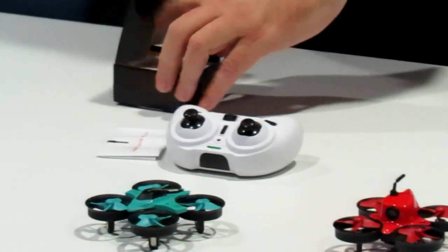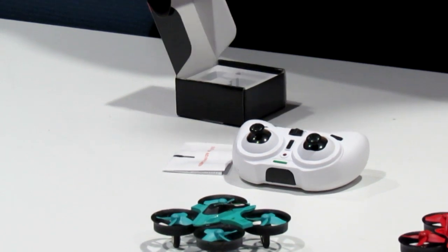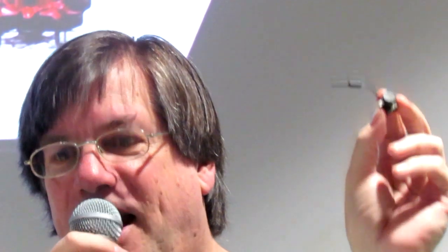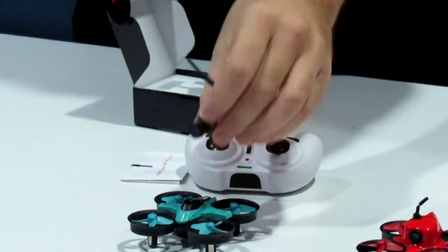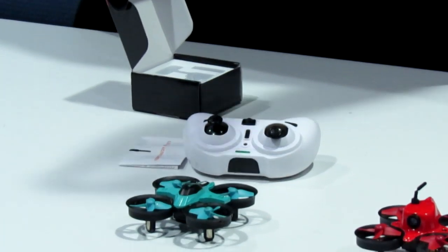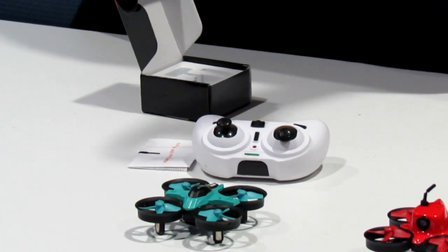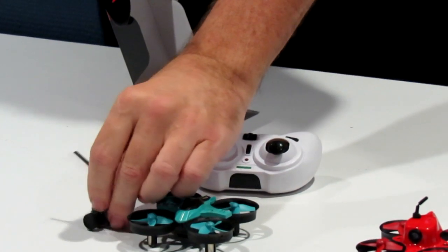And I found online you can buy these little tiny 1.5 gram cameras that transmit NTSC on 5.8 gigahertz. You can get these for about $4. And there's a lot of YouTube videos that take one of these and glue it to the top or bottom of one of these. And so now you have a drone with full video FPV that you can fly around for about $20. Really, really cool.